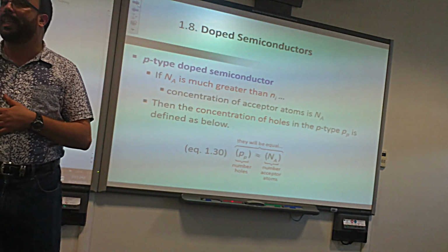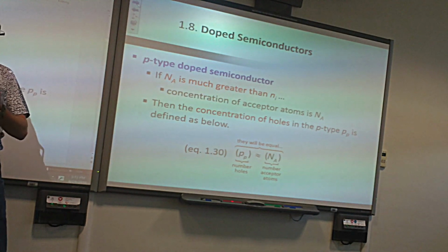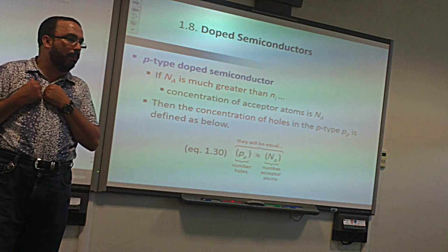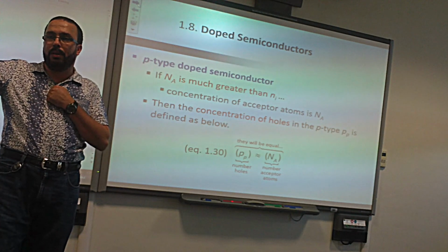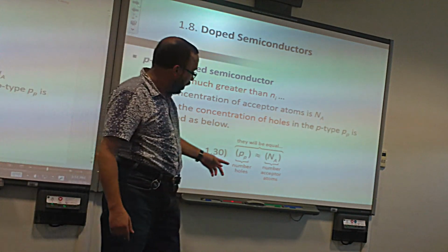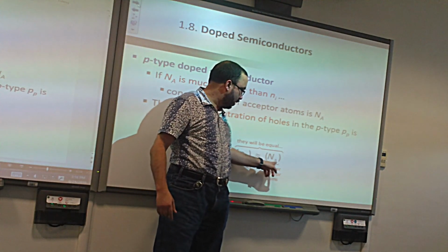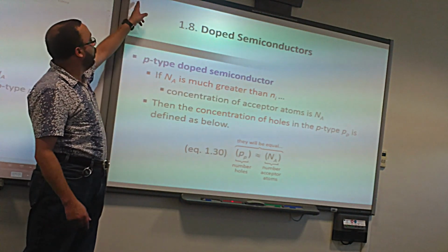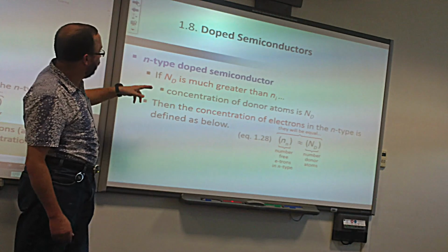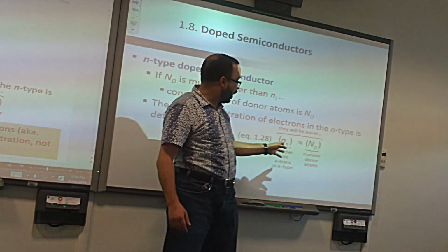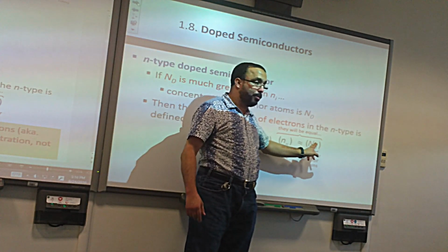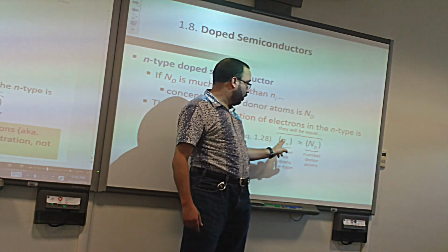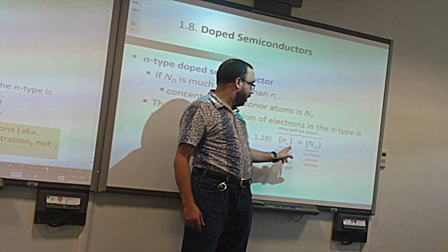We call them acceptors, because boron accepted an electron from outside to create a hole. Yes or no? We call it acceptor, and that's why N means here the density actually, and A means acceptor. Excellent. The same thing for the donors. The donors, which is in this case the phosphorus, they are responsible for all the electrons in the N-type semiconductor.